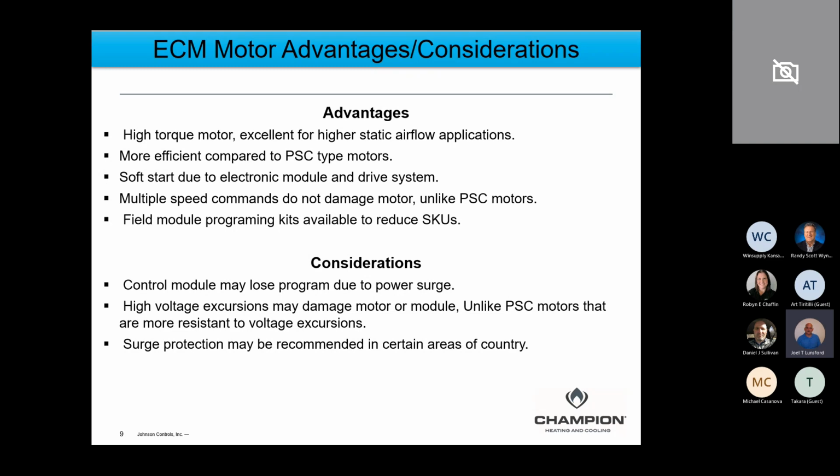Now, with all that said, of all the motor technologies that we have available to us, if you have an older home that has marginal ductwork behind sheetrock, or in an area that you cannot access and remediate, the one motor technology that will help overcome that static and basically push air where nothing else will push is an ECM type of motor. So even though it's not a cure-all, it will definitely improve your airflow if you have marginal ductwork in an older home and you just can't get to the ductwork to fix it.